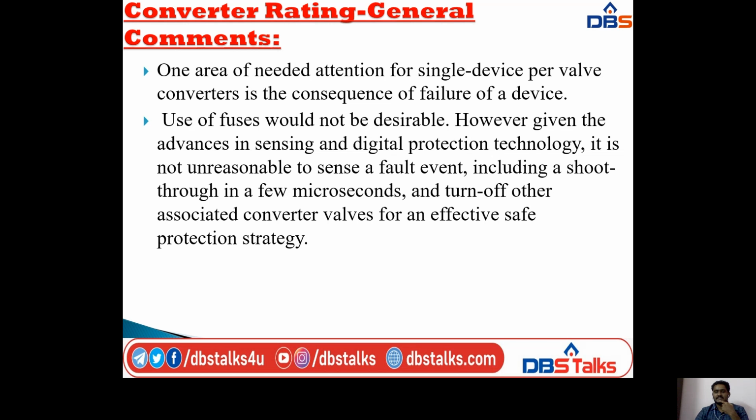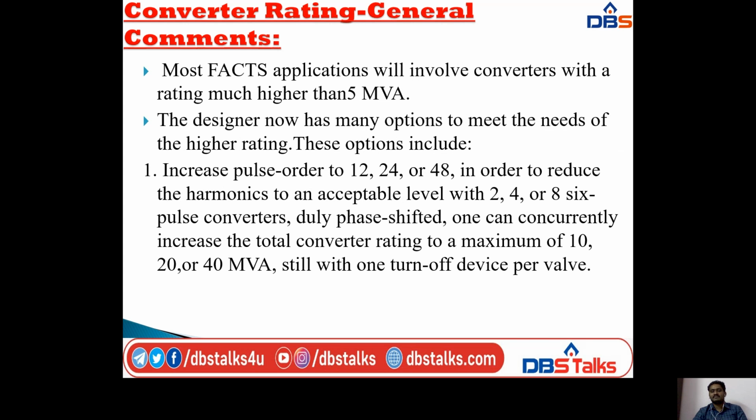However, given the advances in sensing and digital protection technology, it is not unreasonable to sense a fault event, including a shoot through, in a few microseconds and turn off other associated converter valves for an effective safe protection strategy. Here, the fuses would not be desirable because of these advances. Most FACTS applications will involve converters with a rating much higher than 5 MVA.